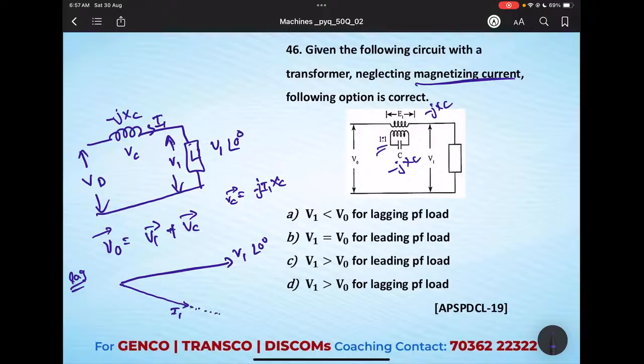We know that this is a pure capacitance, because they told us all other losses are neglected. In a capacitive load, the current leads the voltage by 90 degrees. So whatever the drop occurring here will be at 90 degrees with the current phasor.